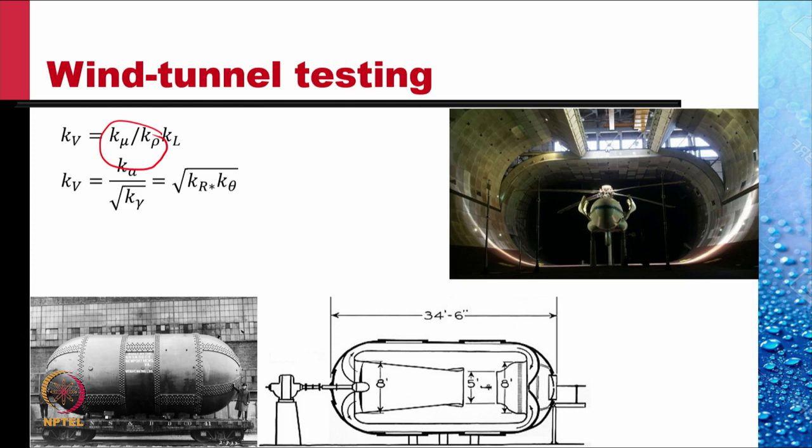So the density is 10 times, and so we can work with the scale model of KL equal to 10, that is 1/10 the full scale model. This was one facility that would be used for testing the components at the same value of Reynolds number as the actual prototype.